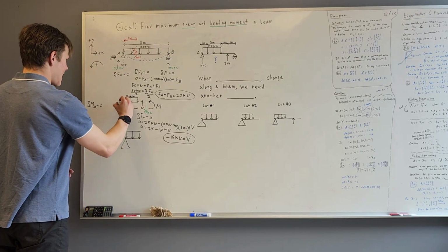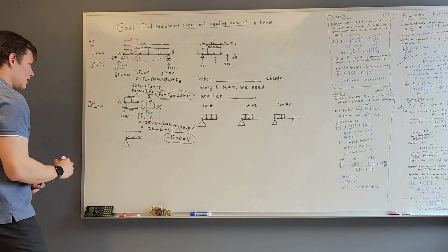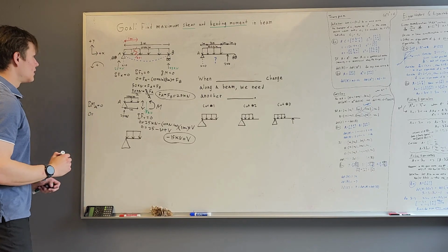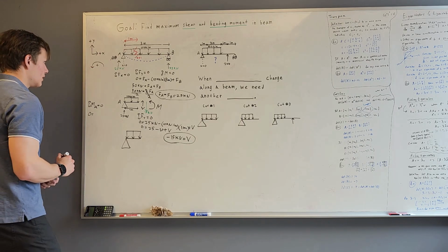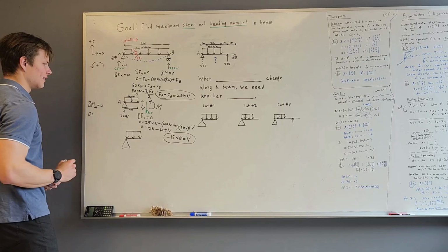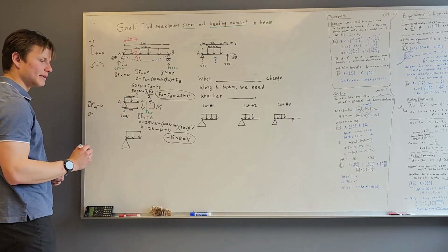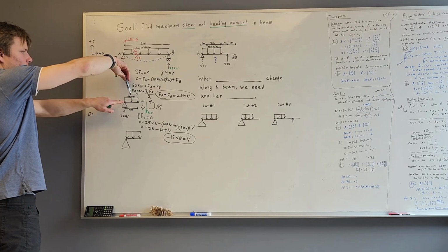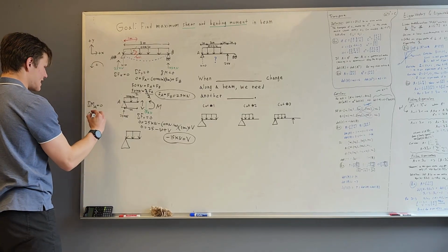So we have A. The sum of the moments around A is equal to 0, and then we know that 0 is equal to, now using this sign convention we have here, we can write out our moments on this side. So we'll have our uniformly distributed load. At A, that's causing a moment that's going clockwise instead of counterclockwise, so we'll have a negative moment.